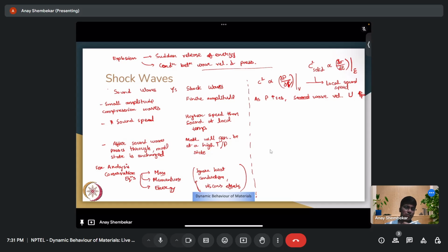That is basically dispersion. At different pressures, you will have different wave velocities. The higher pressure component moves slower, the lower pressure component moves faster, and with time the lower pressure component will move far ahead, whereas the higher pressure component is yet to reach. So whatever pressure pulse you have will slowly start widening if this condition is not satisfied. When this condition is satisfied, we'll have a picture that looks like this.